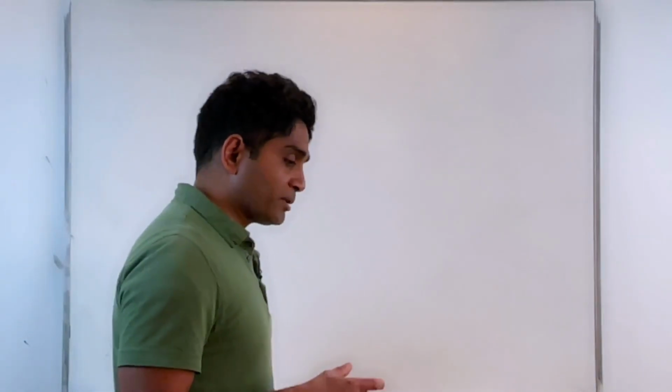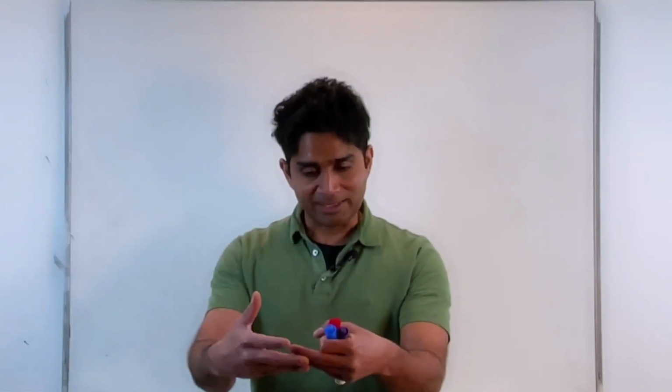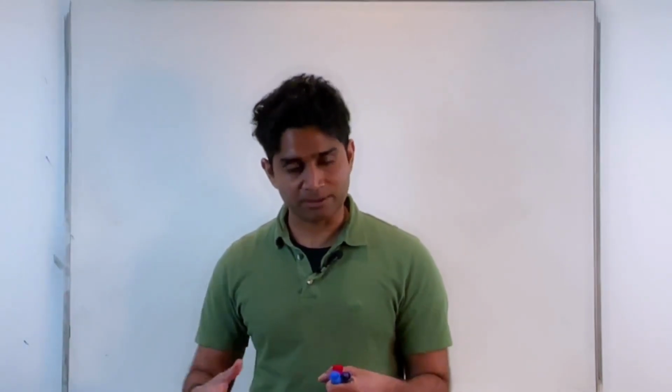As the name suggests, D flip-flops are data flip-flops, so I can use them to store data. In the last few classes, we looked at the construction of a register. You can think of a register as a temporary memory location that can be used to store data. You can load data as a parallel load operation, directly from the data bus in a single clock pulse, synchronized with the clock, into all of the flip-flops constituting the register. That's the parallel load operation, called the parallel register.